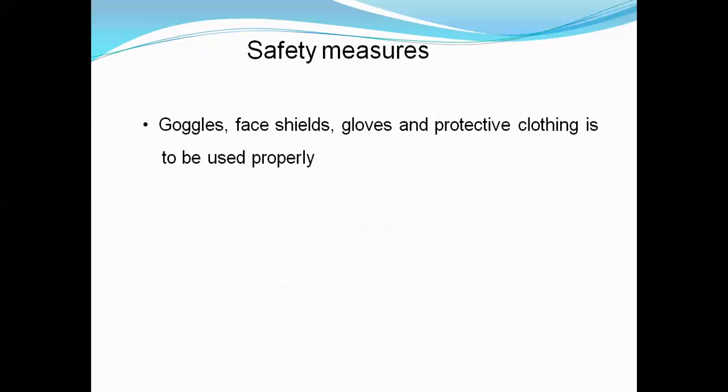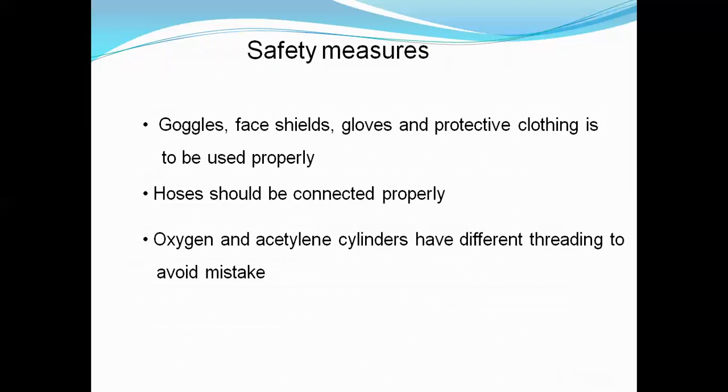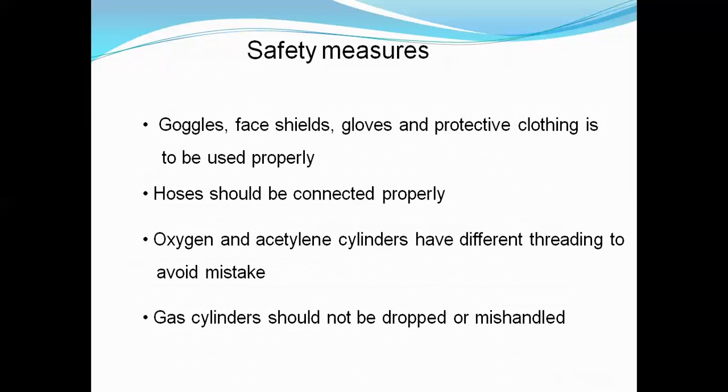Safety measures: goggles, face shields, gloves, and protective clothing are to be used properly. Hoses should be connected properly. Oxygen and acetylene cylinders have different threading to avoid mistakes: right hand threads and left hand threads. Gas cylinders should not be dropped or mishandled. These are the safety measures.